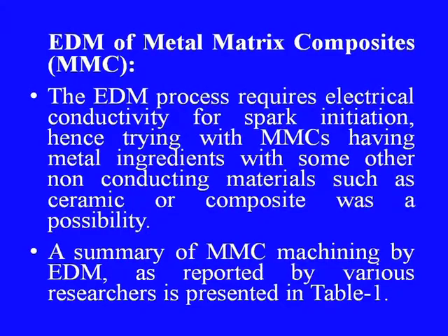Then let us look at the possibilities of electric discharge machining of metal matrix composites, which are also commonly known as MMCs. The EDM process requires electrical conductivity for spark initiation. Hence, trying MMCs having metal ingredients with some other non-conducting materials such as ceramics or composites was a possibility. A summary of machining of MMCs by EDM is shown in the following table, which we will see shortly.